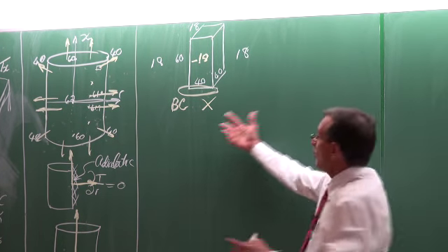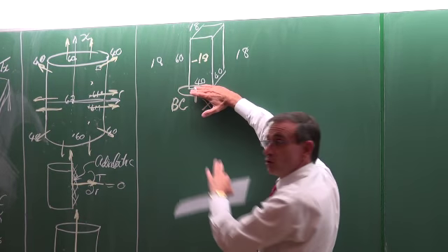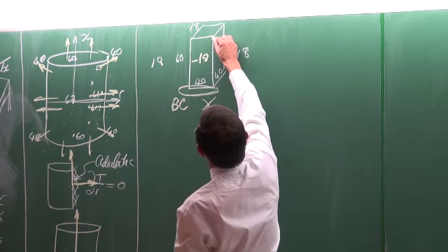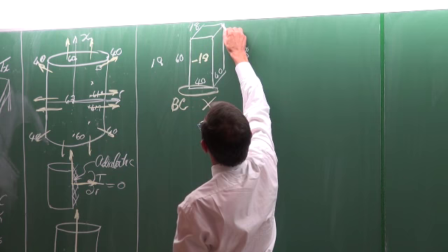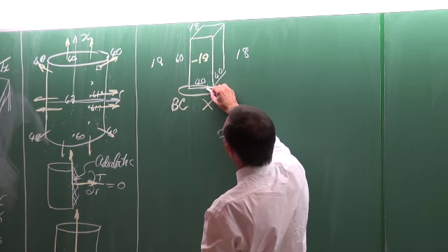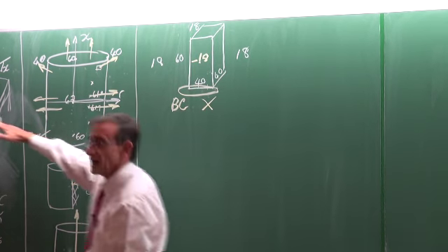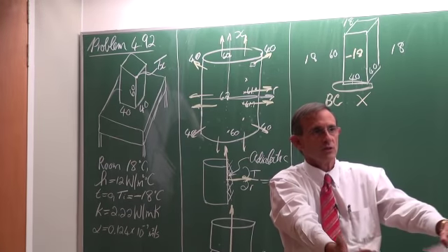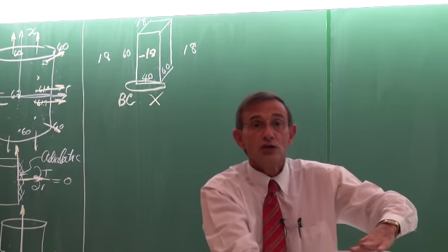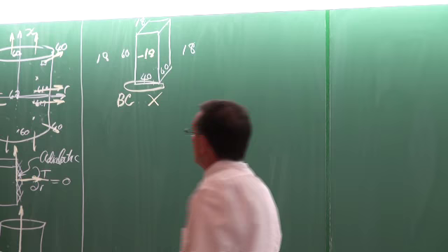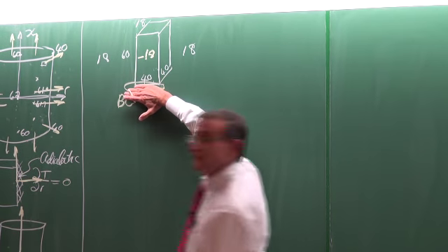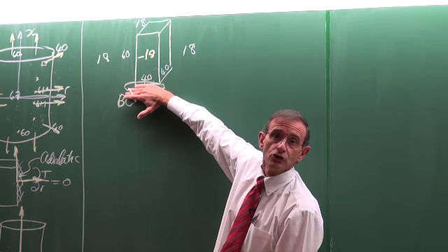But again, if you now think of this problem, if it's going to stand on the table, we know that it is going to start melting on the four corners. The heat transfer is not going to go through the table because, as the problem stated, we can assume that is negligible. So what we have there is actually a symmetry boundary condition.